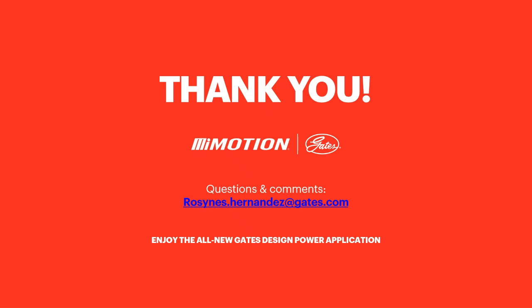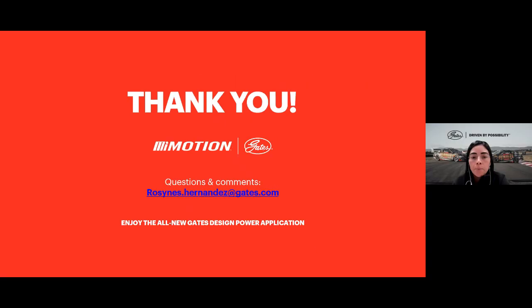Yep, thank you, Rosie. So we have a question here from David. Is there a reason or preference for whether the idler goes inside or outside in a setup? Well, as I mentioned before, the position of the idler depends on the rotation of your belt drive. Remember, what we need to be sure of is that the idler is always positioned on the slack part of the belt, not on the tight part. If you position it on the tight part, you will have a failure.